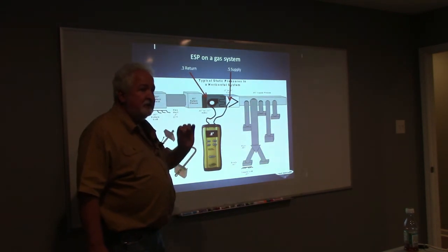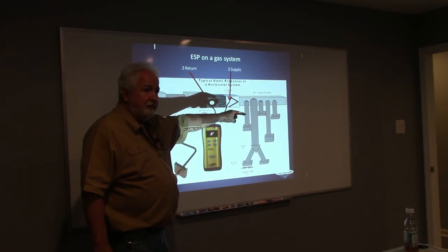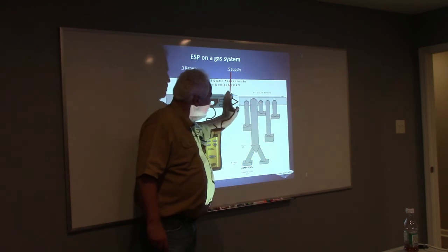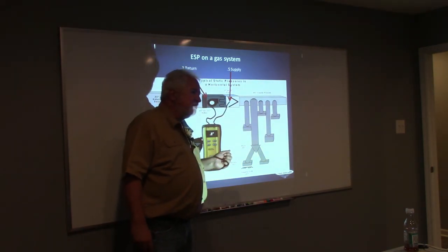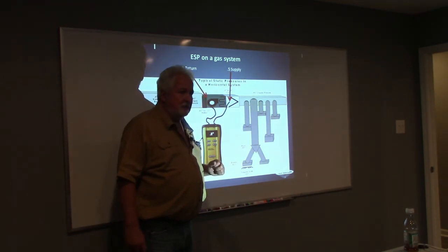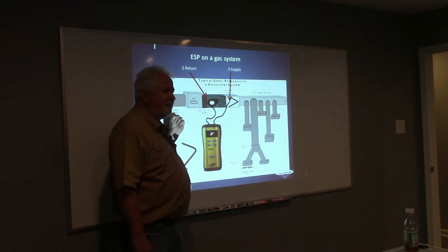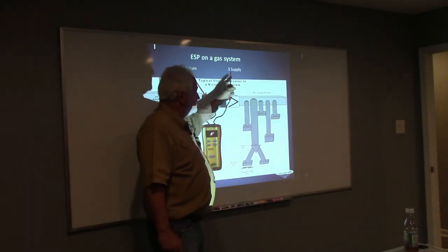Never do you want to see your resistance on your return side higher than your supply, because this means it's having to blow through all of that. So the static is going to be higher on the supply side. It's a blower, not a sucker. It was never designed to be a sucker. So if I have more resistance here, the fan is operating very inefficiently. Does that make sense? Cool. So always lower than the supply.